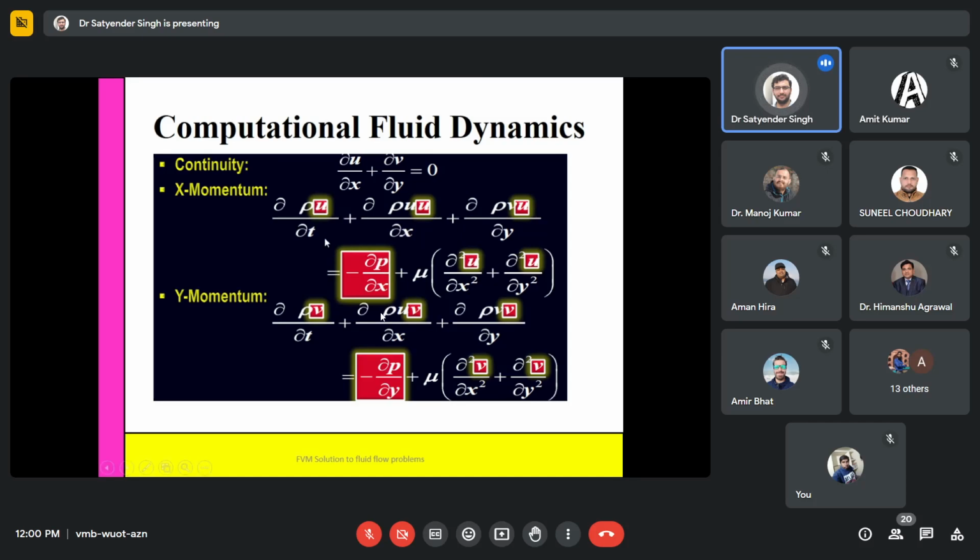Okay, for the first instance, I never told you we will rearrange the equation for pressure. I told you in the whole discretization we will discretize all the differential equations for the u variable only. Similarly here for v, where p will also be present in the discretized form in the same equation, and will be one unknown for us.